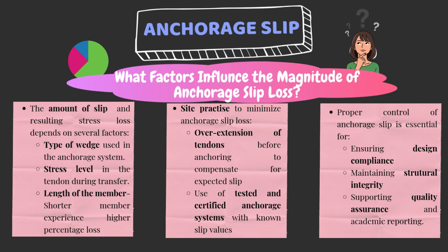First, the amount of slip and resulting stress loss depends on several factors, like the type of wedge used in the anchorage system, then the stress level in the tendon during transfer. Next, the length of the member. Shorter members experience higher percentage loss.